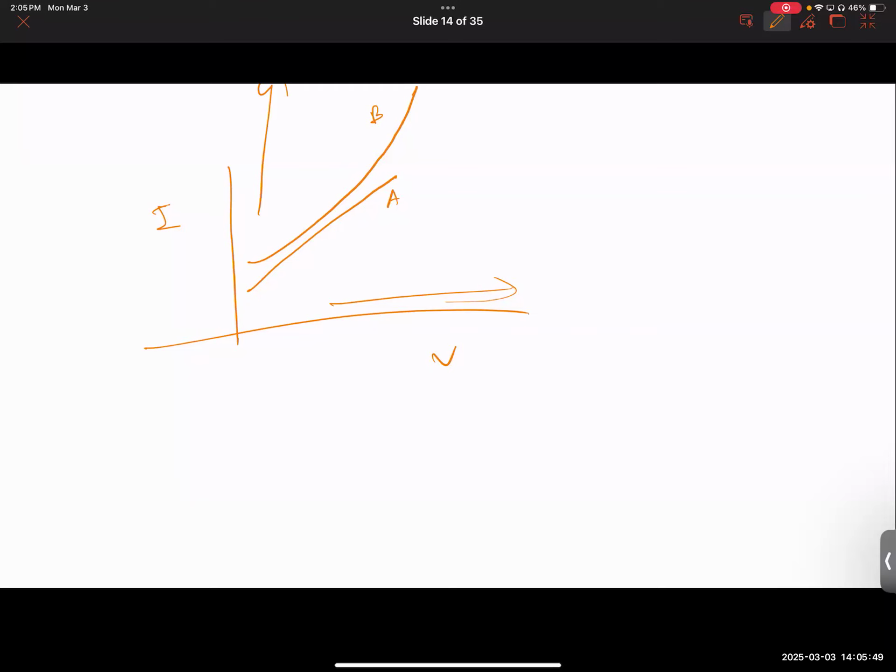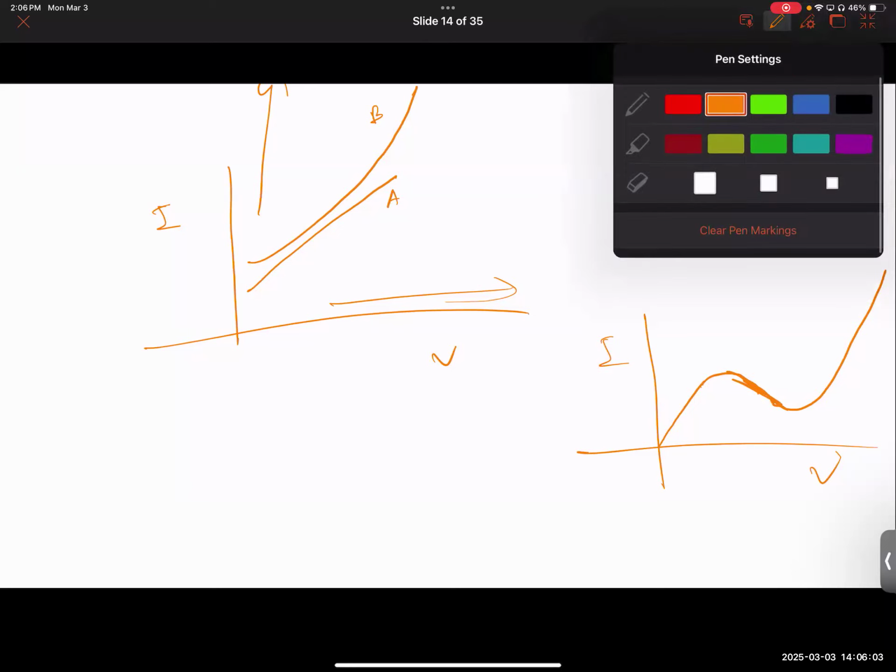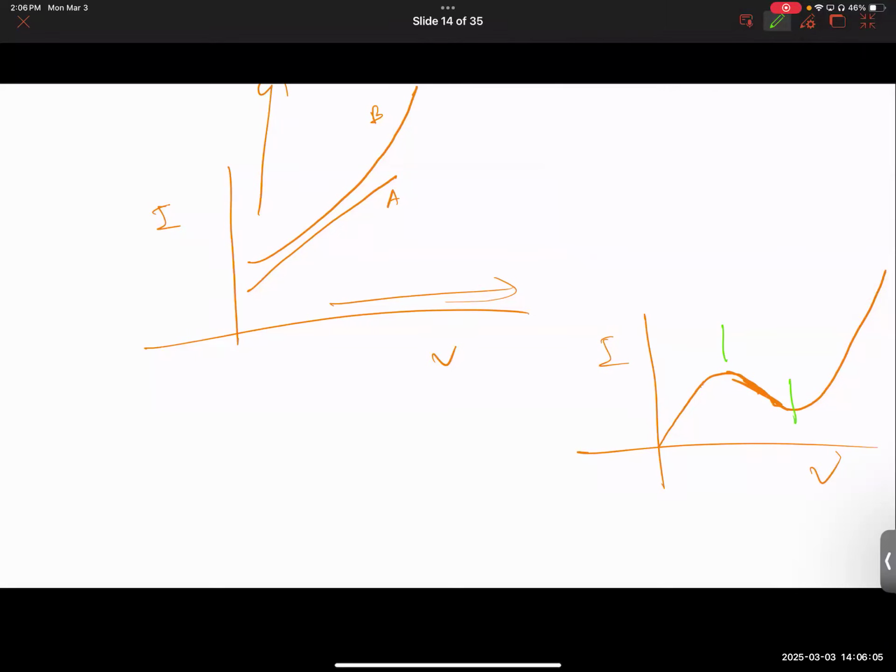Remember, in tunnel diode, we had a situation where in current versus voltage, yes, current increases with voltage, but then it does the opposite. And then it takes back to the previous path. So in this region, how do we even explain what's going on here? Notice your current reduces with applied voltage. So if you take the derivative here, the slope, as you see, is related to resistance.